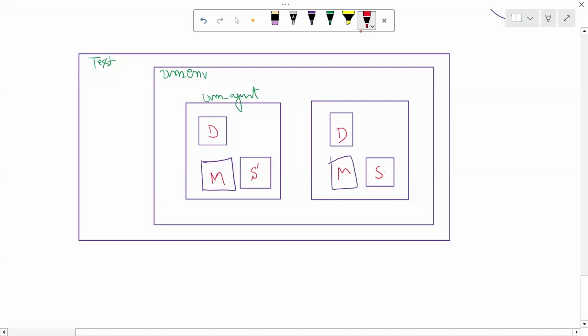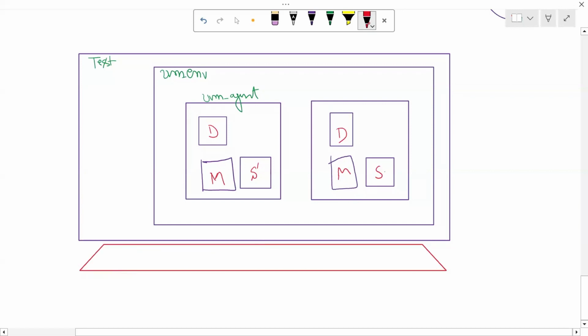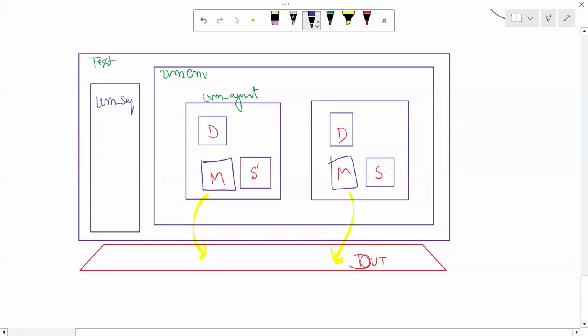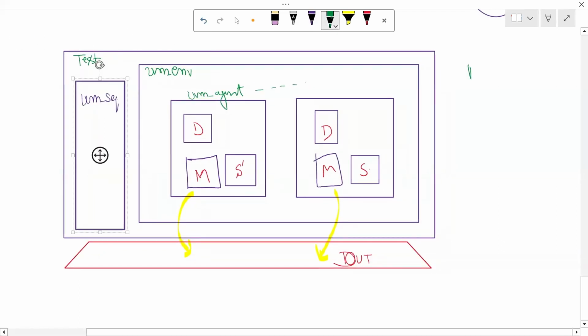This structure is universal and the same structure is currently used by all industry, so there is no compatibility gap. This is our DUT, and it should be connected with the interface. Instead of the generator, here we have UVM sequence. This is the standard followed by all the industry. If we require multiple agents, we can just increase the count, because our universal test bench is reusable. We can reuse and configure it. Configure means we can increase or decrease the number of agents.